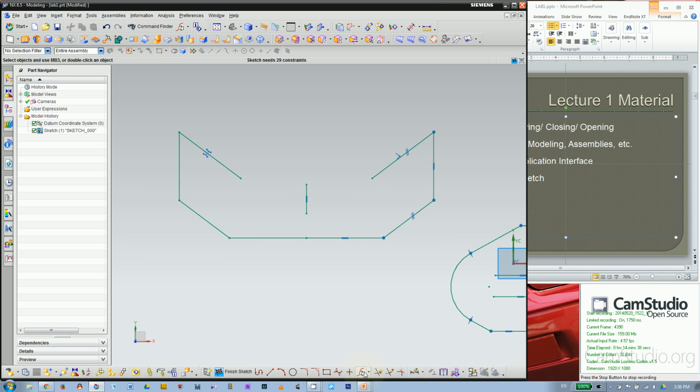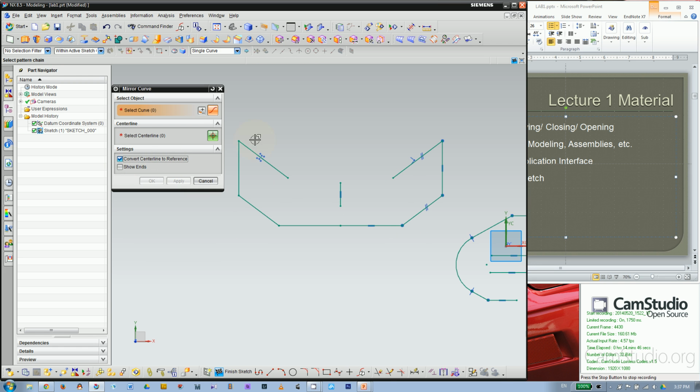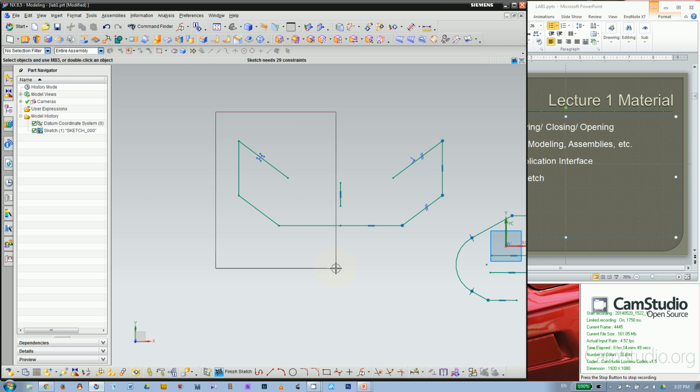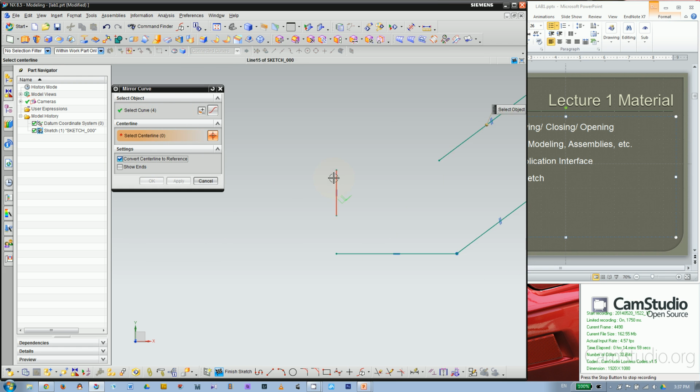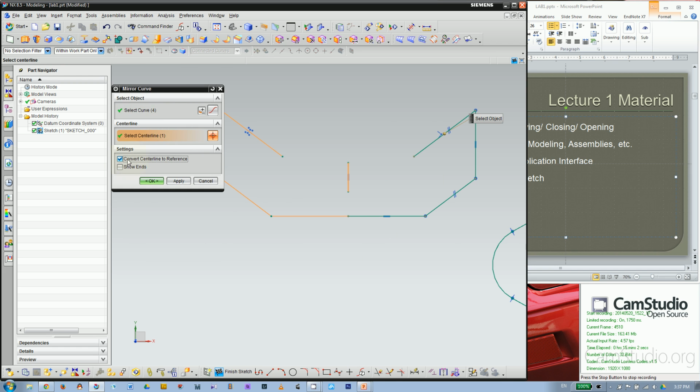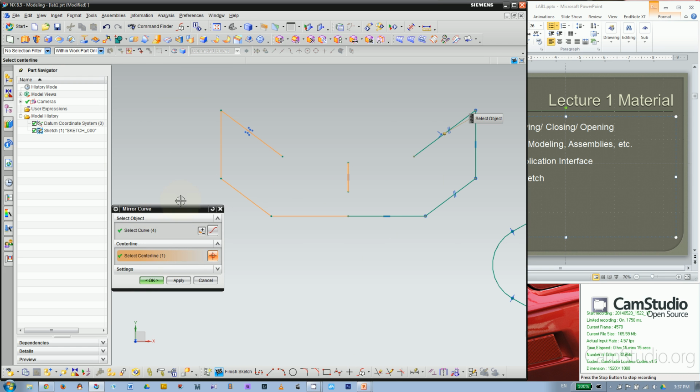All right, and another thing is, I think by default this one's checked. Once you mirror this geometry, the center line is not a solid line anymore because this setting is on by default. So by default, it will look like this. The setting is not shown here, and actually you can turn off this. But let's just show you what's default in NX.